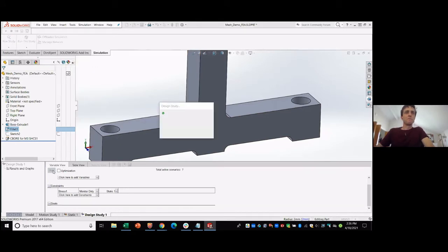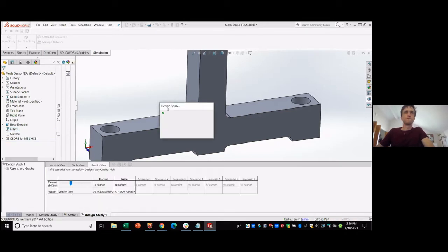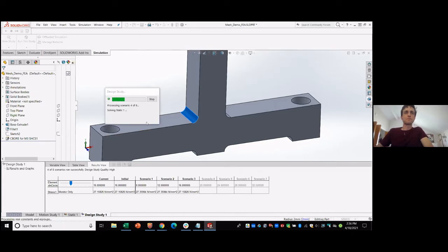And we'll just run. And it's going to run through, and it runs the initial case, and then it runs scenario 1. So all of this creating a mesh and then solving the problem is happening in the background. So you could think, oh, it's going to take forever if you pick options that are too detailed on your high end. But you can hit stop at any point, and it'll finish its current calculation and then leave the others grayed out.